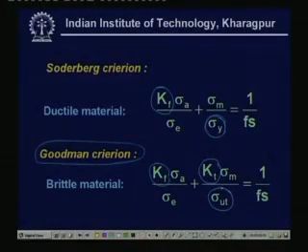So, it is customary that one should take up the theoretical stress concentration factor for the sigma mean in the brittle case, whereas in the case of the ductile material one need not consider the values of Kt for design purposes.